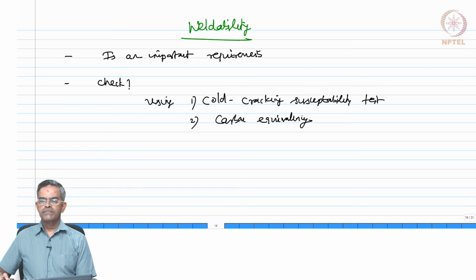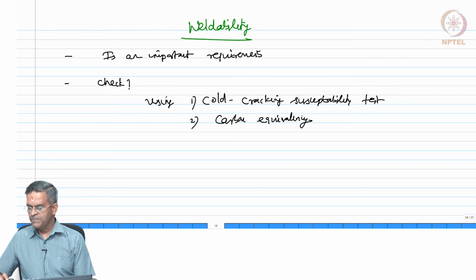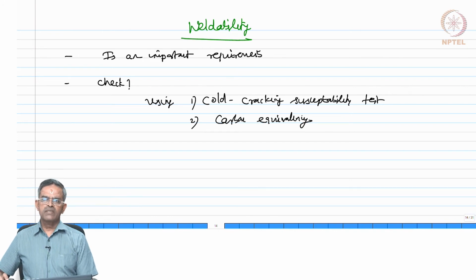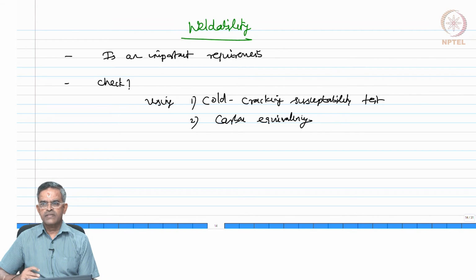From the chemical composition of steel, if you know the components present in steel, each component by weight, based on that composition by weight, one can compute carbon equivalency. If you know the carbon equivalency value, you already know how to group them. We discussed that in the previous slides. Now we want to see how, based on carbon equivalency, one can check its weldability. Let us be very specific about this objective at this moment.